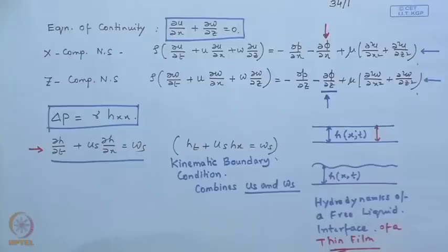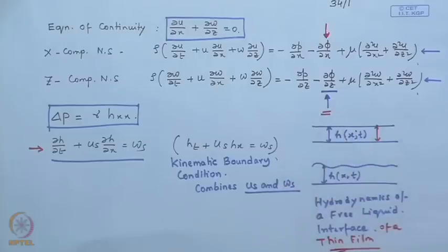You can use this form of Navier-Stokes equation for all your fluid dynamics derivations so far, because do not forget that phi will definitely be a function of h, the film thickness, and if your film thickness is higher, in most cases h will have some exponential power and be in the denominator. So, for higher values of h, phi will tend to 0. Therefore, this term has no significance in macroscopic derivations or deductions, and we often tend to neglect it, but there is absolutely no problem if you have this term intact in your macroscopic derivations as well.